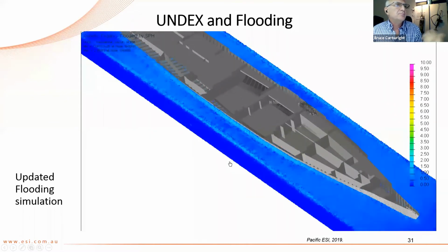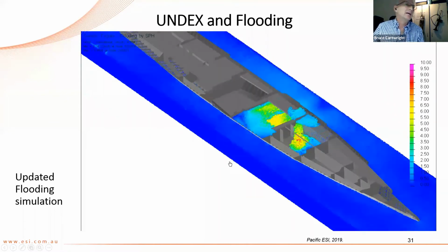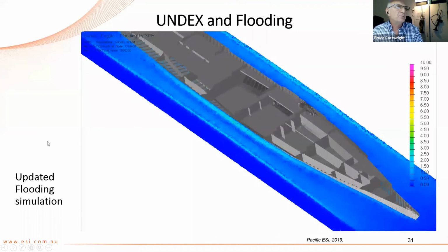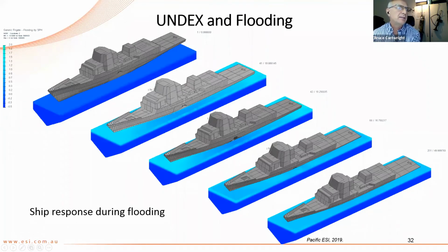We're just modeling the fluid and the structure interaction with some very simple rules as to how they interact. So here's just 4 snapshots throughout that simulation. In the top left, the boat starts out of the water to make sure there's no water inside the boat, sorry. The tank is a kind of unusual shape, but it's just big enough to keep the minimum number of fluid particles and then allows the boat to float. In that second step there, it has its hydrostatic equilibrium. Then we remove the patch off the side, the water comes in, and you can see the boat acquires a list.